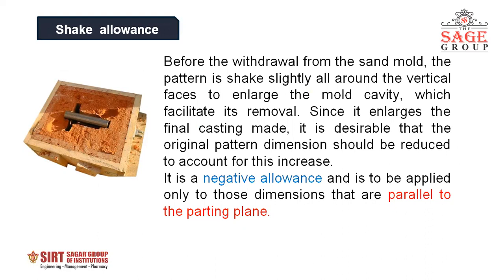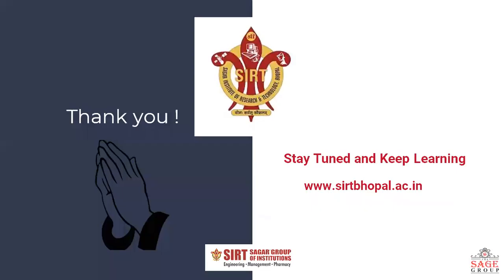All allowances are positive, only shake allowance is a negative allowance, and it is applied parallel to the parting line because shaking enlarges the cavity parallel to the parting line. So this is all about pattern and its allowances.